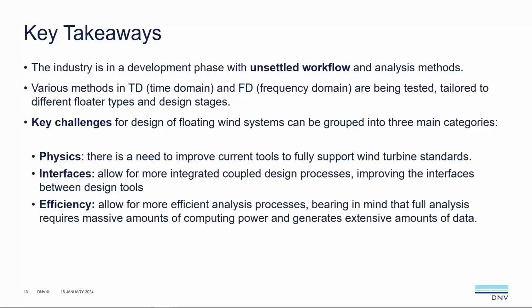Does the 9% frequency difference refer to the difference between the finite element method result and beam element result? Yeah, exactly. That's right. This is comparing the coupled frequency derived from an FEA model that accounts for all the complex features of the structure, the scantlings, everything, compared to the simplified beam model.